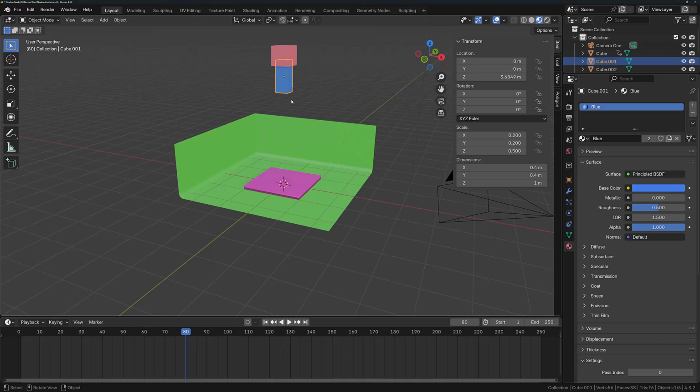Another way of creating a keyframe is to just find the value within Blender's user interface. So here, the only actual value that we're changing is going to be the Z location. As a result of this, all I need to do is actually press the I key, and the location transforms exclusively will have keyframes added to them.